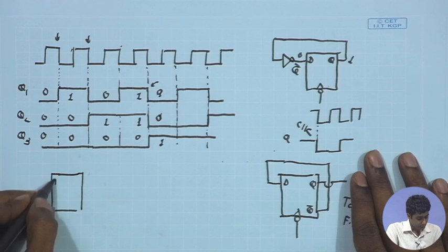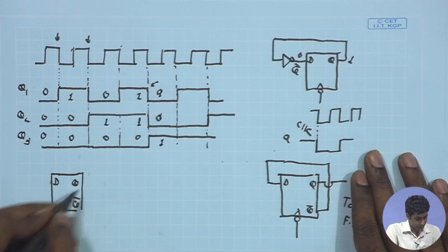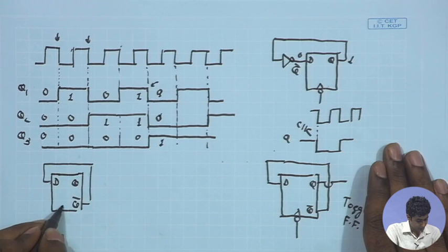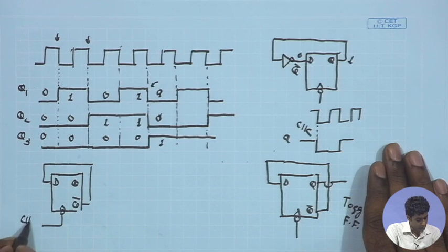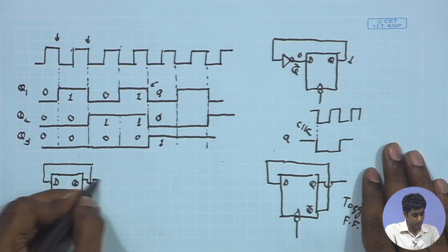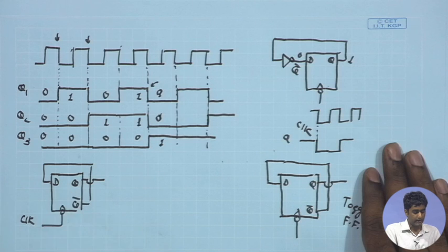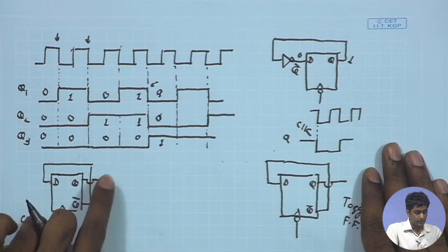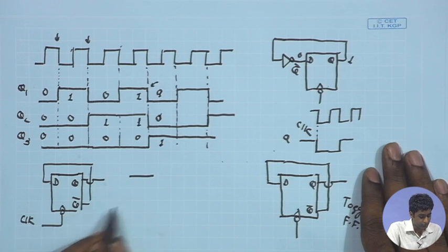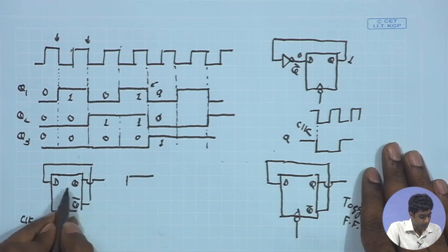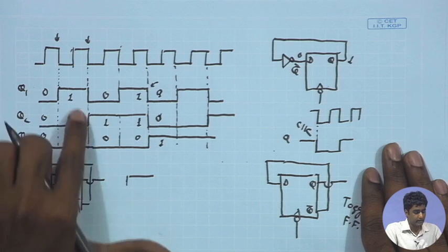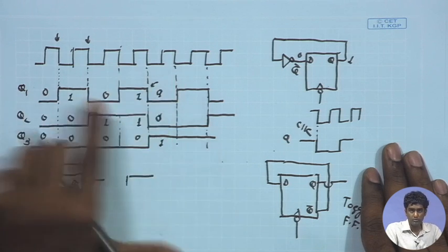So, I have these. The first one is going to receive the main clock, which is going to make this one toggle at every negative edge, and then I would like to put the Q of the previous flip flop as the clock of the next flip flop. So, if I call this Q1 and D1, whenever Q1 is making a negative transition, the Q2 toggles its state.